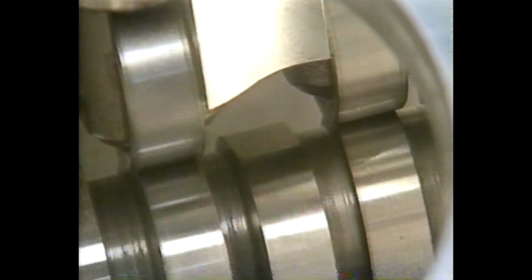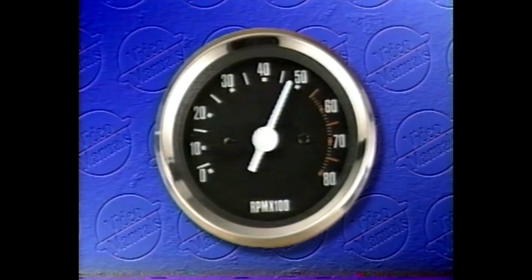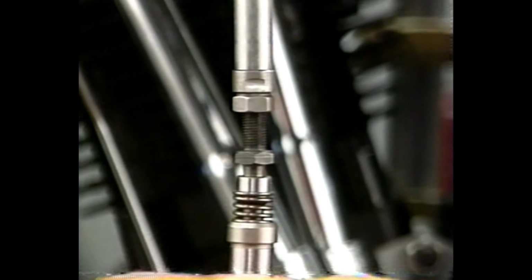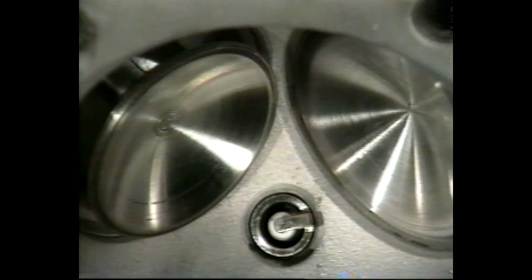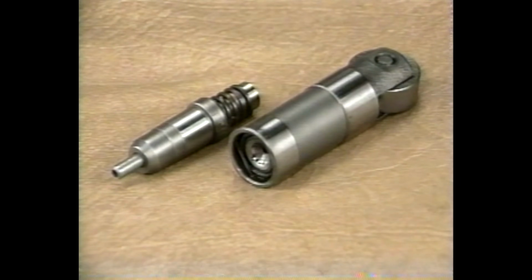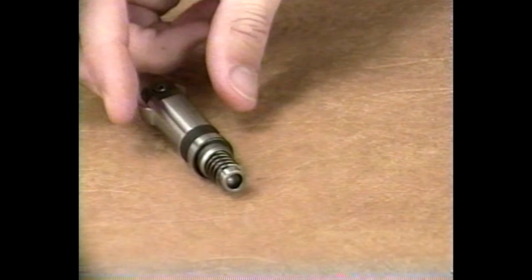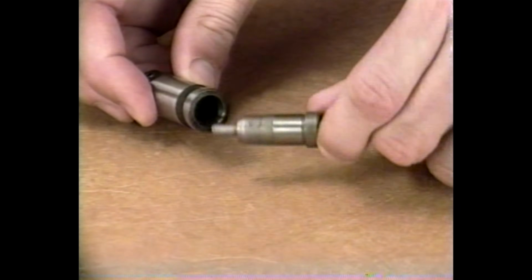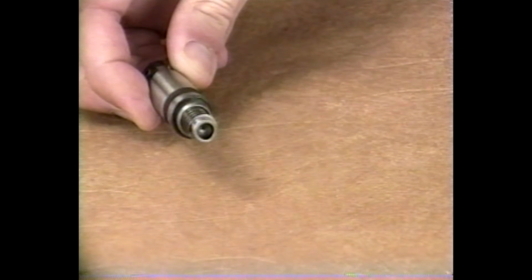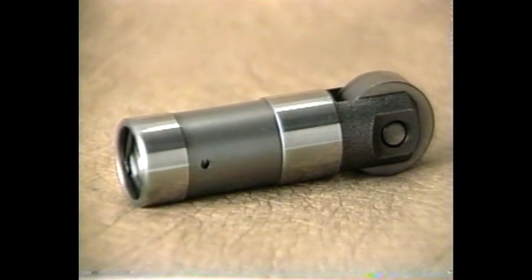The oil pressure is also dramatically increased when we run our engine at high RPMs, creating the same problem of overpressurized lifters. This is often referred to as the shock absorber effect. Once again, changed valve timing causes the valves to float, and our engine loses power and runs rough. The problems of pressure-sensitive hydraulic lifters become worse as they start to wear and lose their closely machined tolerances. Shovelhead engines suffer this problem much more than the evolution engines, since the hydraulic lifters of the shovels are not machined with the same close tolerances as those of the Evo lifters.